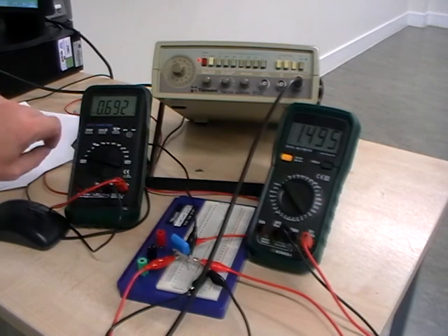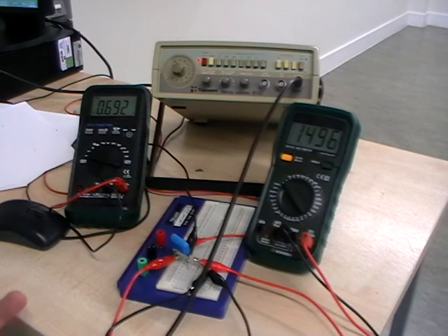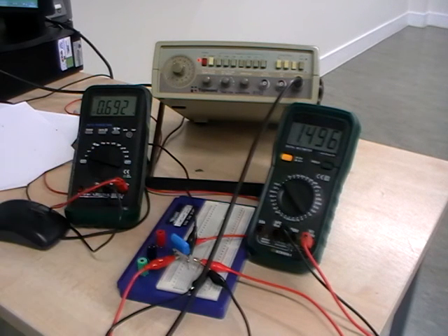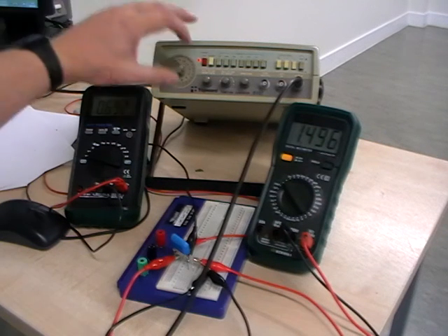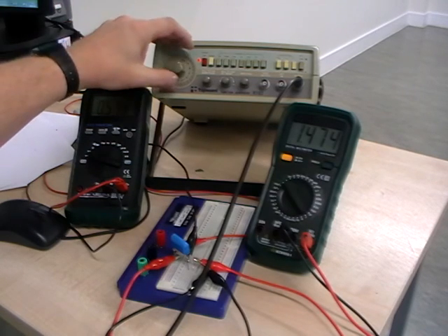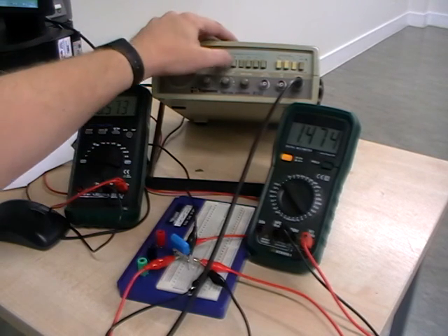So it's dropping less and less voltage, which means that the reactance of our capacitor is going down. Always remember, big resistances drop big voltages. Small resistances drop small voltages. So the reactance of that capacitor is getting down and down as we increase the frequency. We are now at about 2 kilohertz. It's 1.8. I'm going to go a little bit higher, and you can see it just goes down further. Okay, let's go really, really crazy and go to 10 kilohertz.